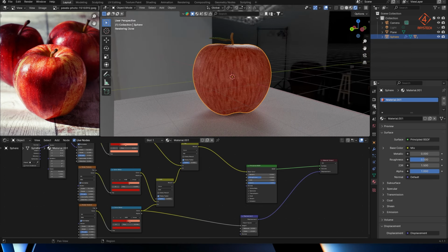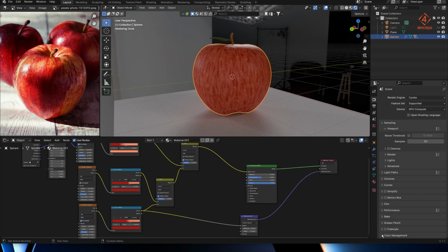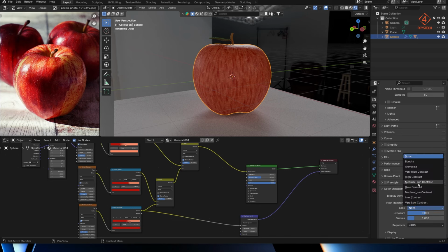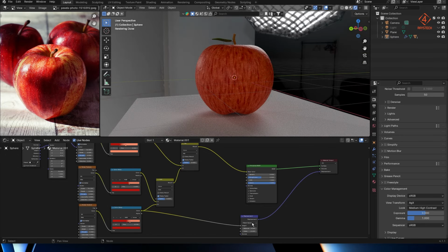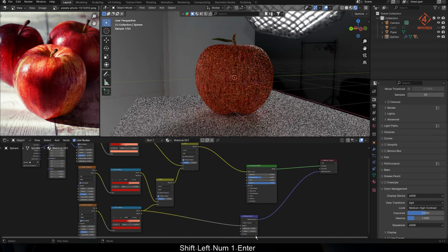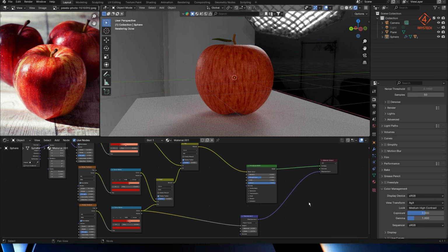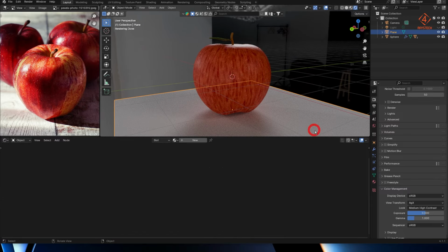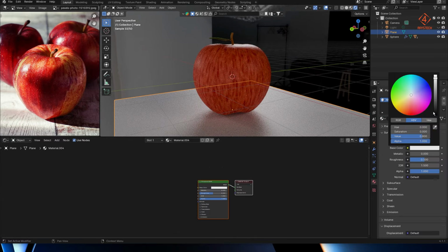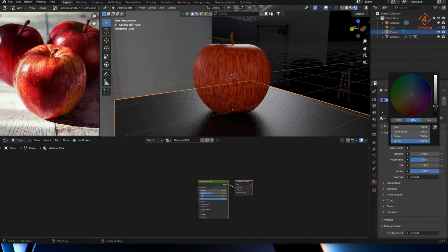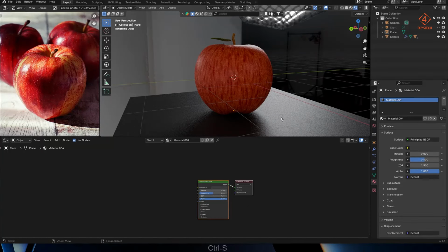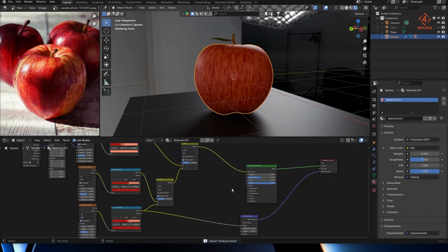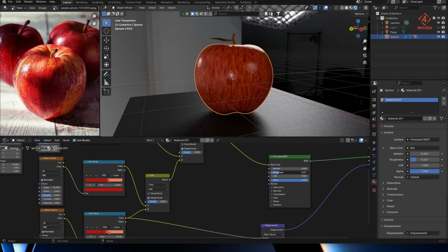Okay, well, we're in a good space. Let's just color manage and set up medium high contrast to this, to get a bit more sharpness into our image. And as I said, there are always little tweaks I'm making as we go towards the render process. Okay, if you go to material, you can change the material of the floor, just making it darker. We will work on removing this completely later on, but for now I'm just trying to make more sense of how things are coming out.